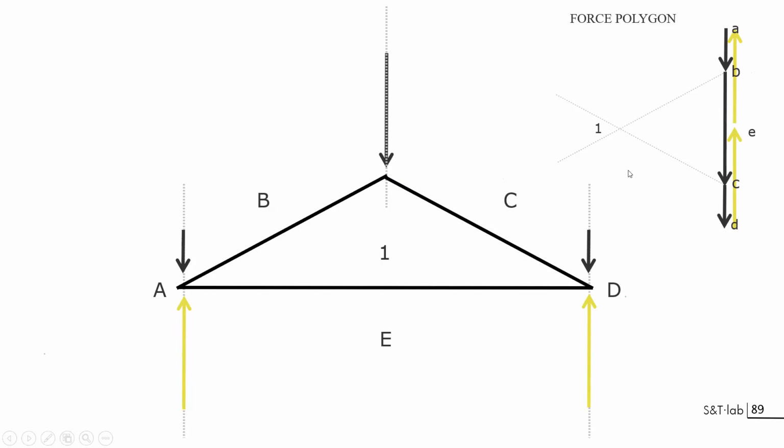This is 1. And what is wonderful with graphic statics is that it will enable you to check this system, since you have still a bar that has to be drawn, and you have two conditions to fulfill. The first is that you know the orientation of this bar, it is horizontal, and the second is that it has to pass through 2 points that are 1 and E. And actually, the solution is not always met, but in this case, you can see that the orientation will be horizontal and passing through these 2 points.